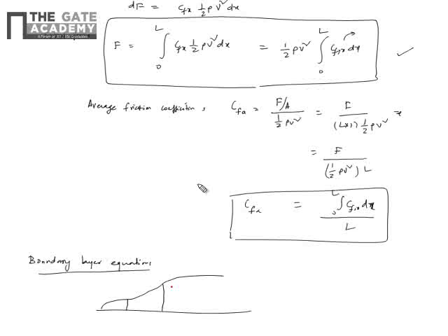Even in the laminar case, you have to basically start from the Euler equation. Starting from the Euler equation, because the flow is viscous, you cannot neglect the shear terms. So you have to take a fluid particle, write down the pressure terms, write down the shear terms, and set sigma Fx equal to max. And the flow is rotational because of shear, so there is some kind of rotation, so you have to consider all those things, and finally you'll end up deriving the equation.